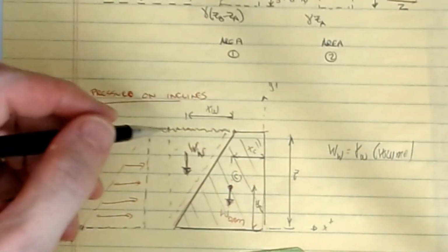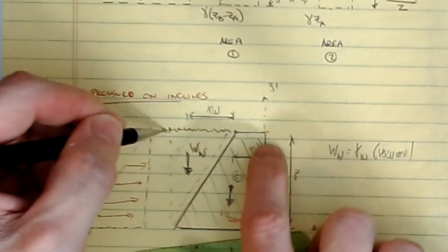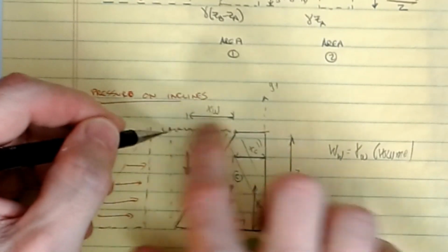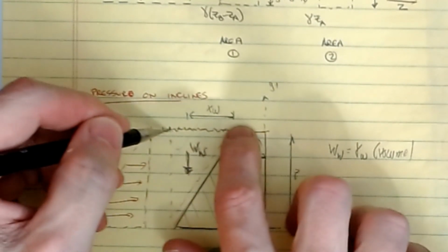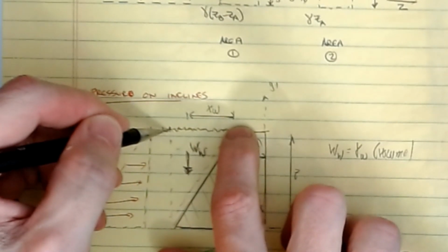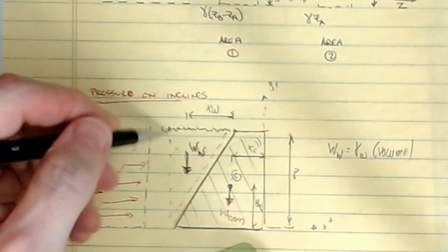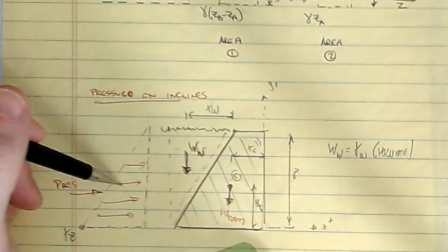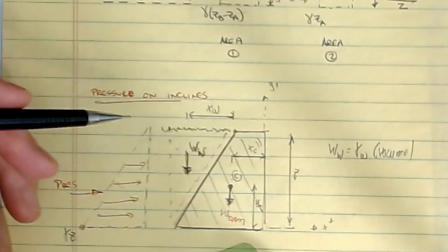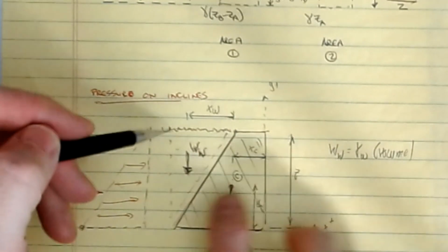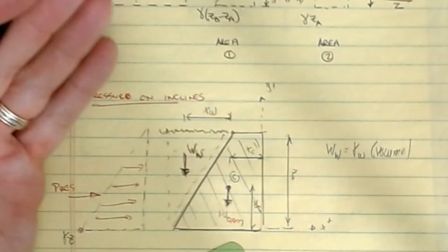If you know these dimensions, say all the way up to the top of the dam, the height is Z, and based on the slope you can know the horizontal dimension. That's one half the height times the horizontal, just like what you were doing over here, but now for the volume of water itself. On a per unit basis, we imply one foot going into the page.